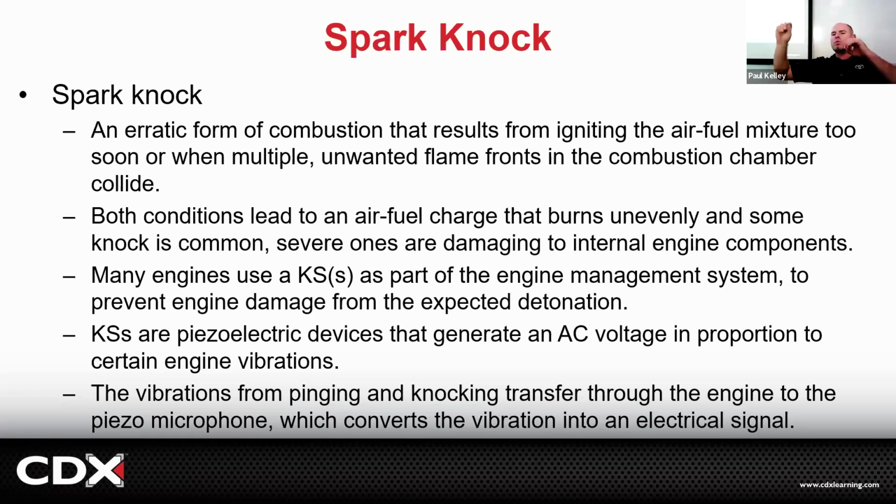And so if we start to lose control of our combustion because of pre-ignition, detonation, or any of these types of sounds, the knock sensor will catch that and say, whoa, we got an issue. We might need to retard the timing. We might need to richen the fuel. We might need to take some corrective action. So when you start hearing the term spark knock, that's going to roll into knock sensor activity, which is all about making sure that the combustion is controlled. The combustion needs to start when the spark occurs, not too early. Makes sense? If it's starting too early, we're starting to lose control of it. We need to make some corrections.